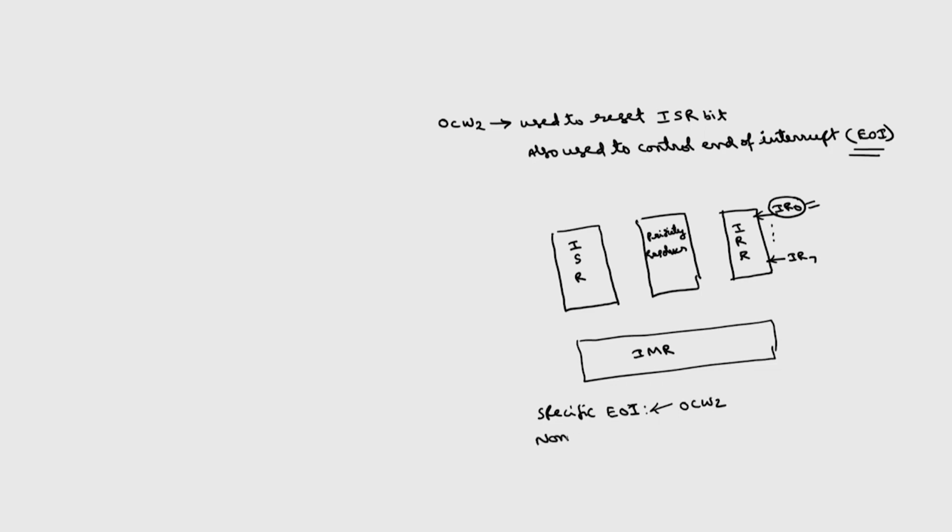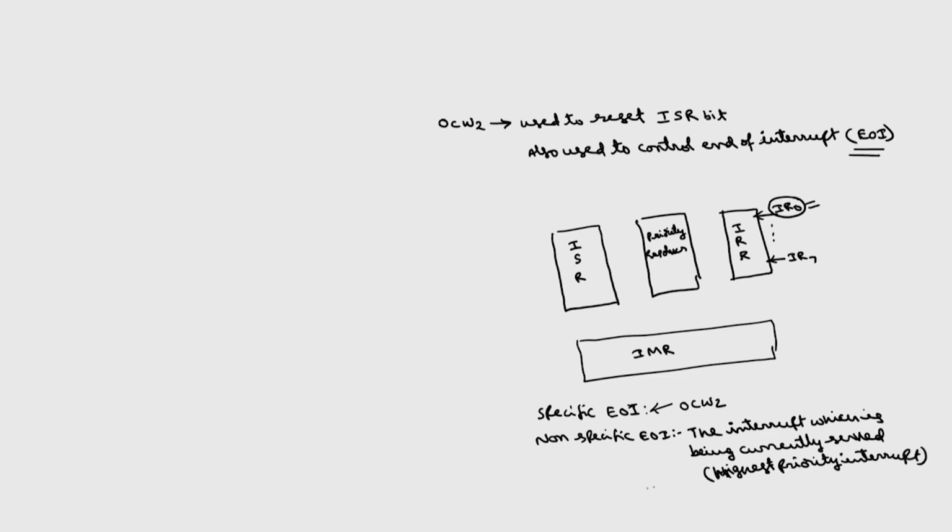Whereas in case of non-specific EOI, as the name implies, by default the interrupt which is currently being served, which is the highest priority interrupt, its corresponding bit of the ISR will be reset.